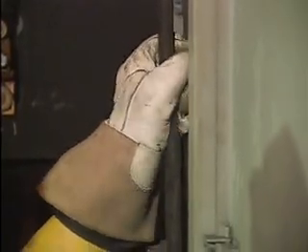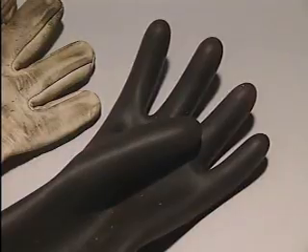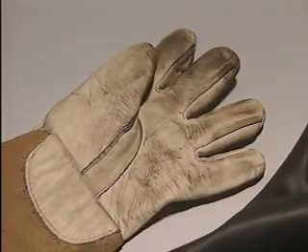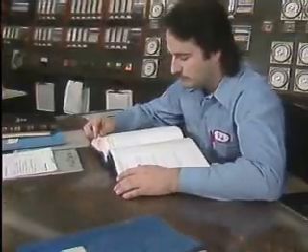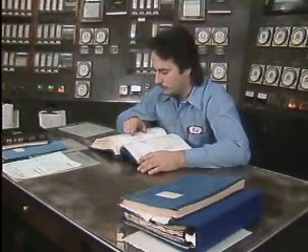When rubber gloves are worn to provide protection from electrical shock, separate leather covers are worn over the gloves. The leather protects the rubber from punctures and other types of damage. Rubber gloves with leather covers are essential protection for anyone who is working around energized circuits or circuits that could become energized. The rubber is the insulating barrier, and the leather protects the rubber. Both materials are necessary. Company procedures and safety manuals typically contain information on when to wear rubber gloves and what types of rubber gloves are required in specific situations.